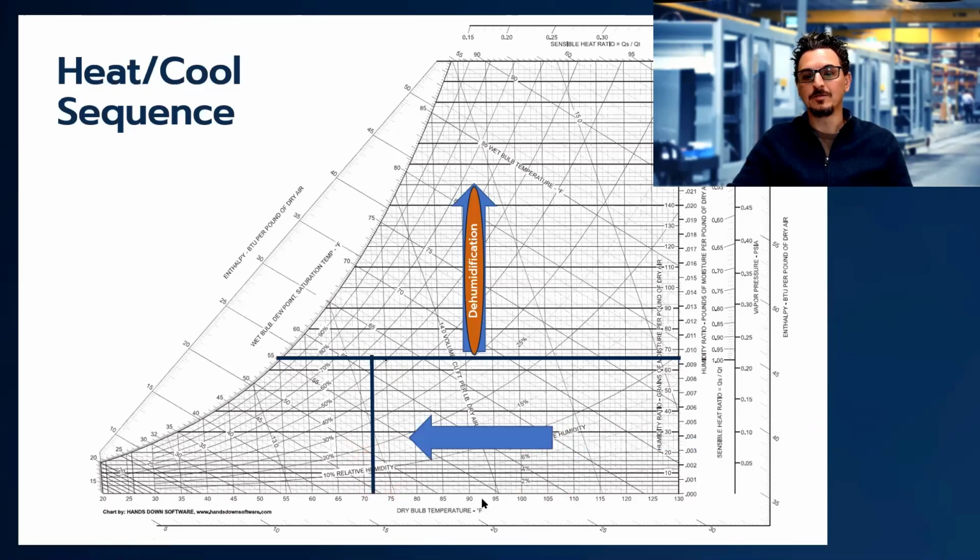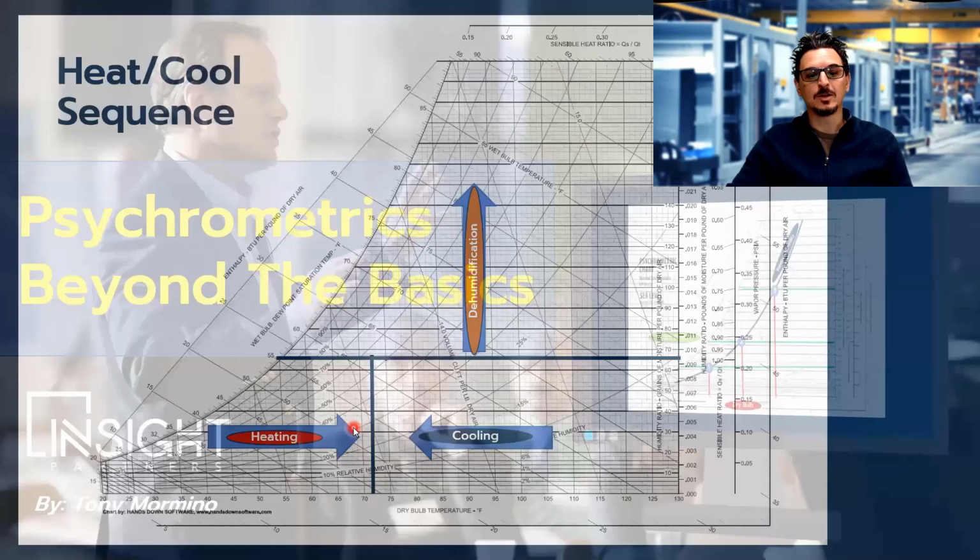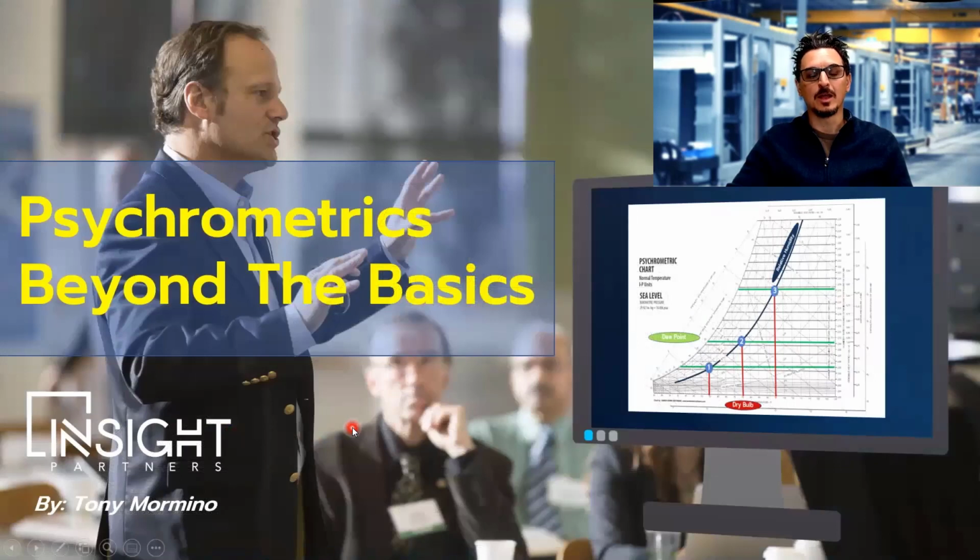So anything above 72 degrees over here, we're going to cool the air down to 72 degrees, just using the cooling coil. Anything below 72 degrees over here, let's say it's a cool day, it's 40 degrees outside, we're going to heat the air with our primary heater, whether gas or electric heat, which are the most common types. We also have something in there called event mode, and we could save that for a more detailed presentation.